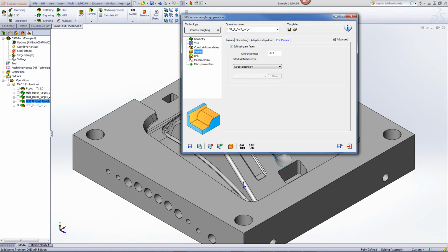If you have it, there is no problem doing a finish with HSM, because that HSM can be converted into a simultaneous motion as well. In fact, in the last webinar in this series, I'm going to try and show you that as well, where if I've created an HSM toolpath, how I can change that HSM toolpath into a multi-axis pass instead.